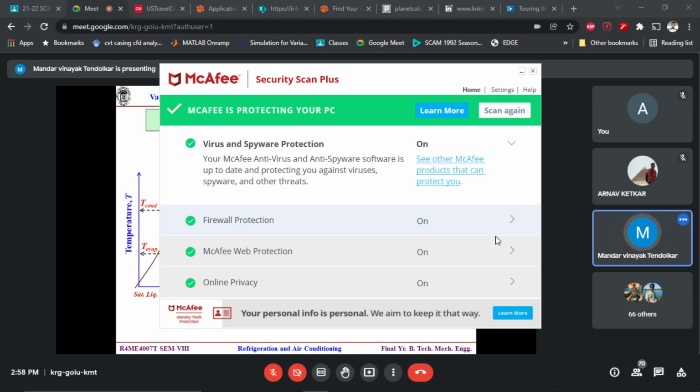So this is a good indicator to analyze the deviation of the standard VCC cycle. What is the meaning of standard? Here it starts at dry saturated vapor compression and starts at saturated liquid expansion. That is what is standard VCC, correct? And Carnot cycle. So my job as a good RAC engineer, HVAC engineer, whatever you call, is that this relative efficiency or second law efficiency has to be as close as possible to 1.